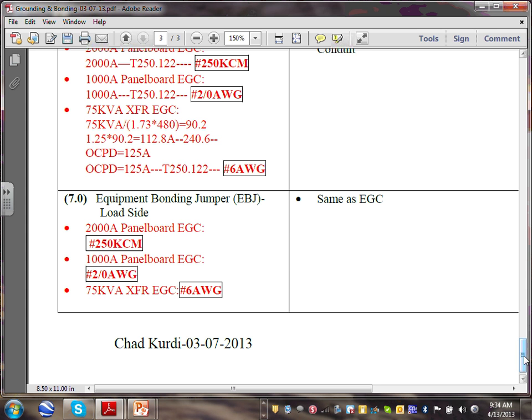But that's your least problem, the arcing problem there. It will not allow the overcurrent device to trip fast enough before it starts a fire. So that's why we care about tightening them. Yes, we're not using it solely as an equipment grounding conductor, but the current doesn't care. It sees a path, and it jumps into that path and goes back to the source when it has a ground fault.